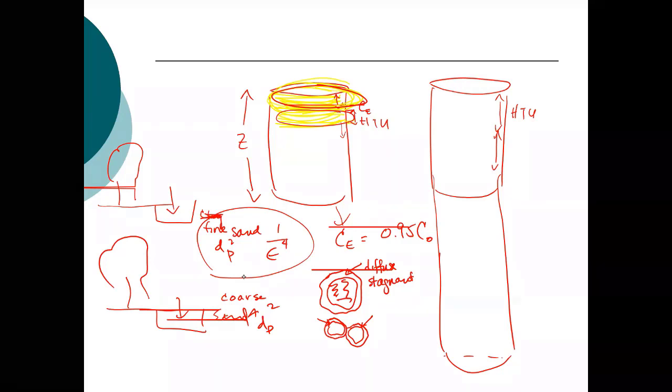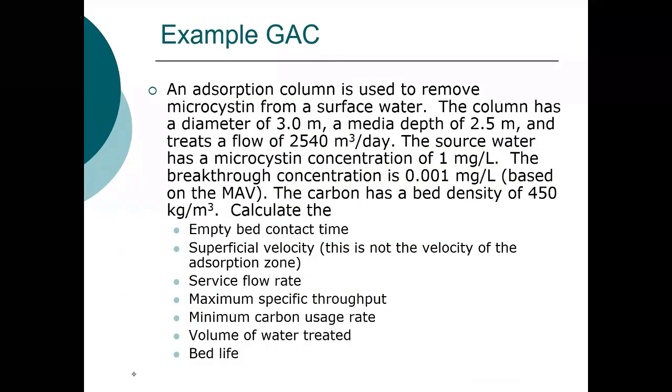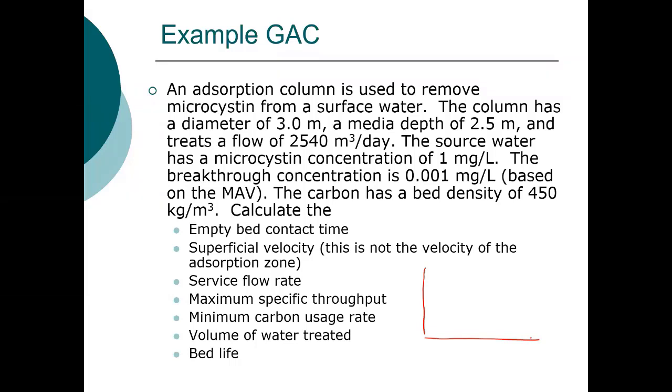I used to make students do the hydraulic grade lines and the energy grade lines in the design. I haven't done that in recent years, but it's important to consider that you would never design a plant without actually creating a hydraulic grade line and an energy grade line for the water flow through the plant. So, extremely important consideration. Let's look at this next problem. Similar problem, but some different terms are introduced here.